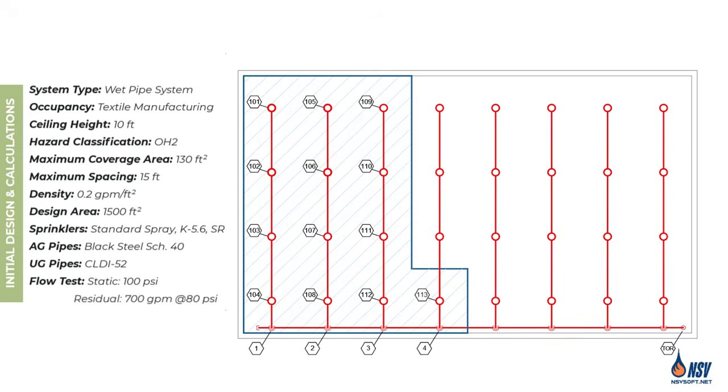Now we need to define nodes for the hydraulic calculations. As explained in the step-by-step video, nodes should be placed wherever the flow rate, C-factor, or pipe size changes. In addition, nodes can be added to make review and analysis easier.